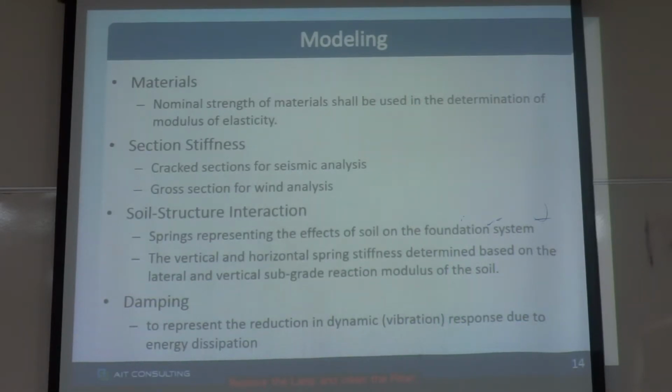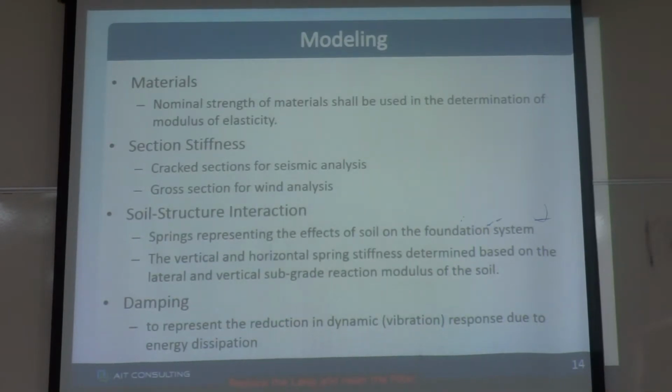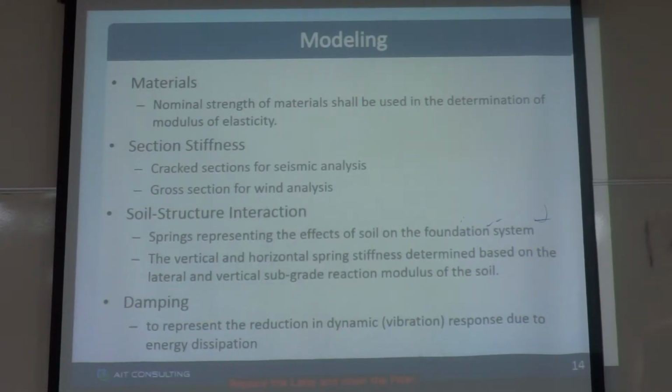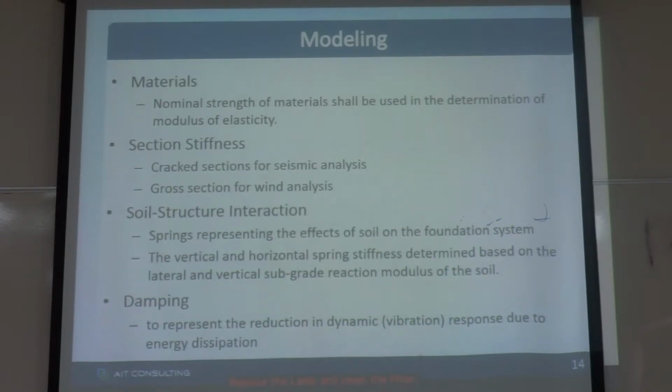Normally people use hinge support or fixed support directly in the model, but we should consider proper soil structure interaction. When you make a fixed support of the column, in reality it will not be fully fixed. There might be small rotation, but you assume that it is fixed. So if you model the soil springs properly at the foundation, you can capture the behavior of the structure accurately.